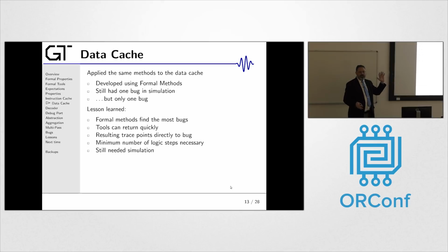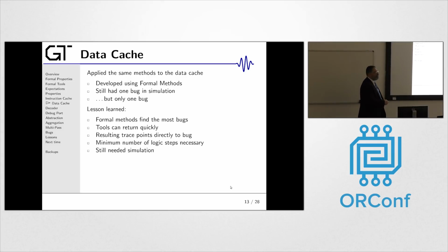Actually, I'm usually working between 1 and 10 gigabytes when I deal with traces. When you're using the formal tool, the trace is maybe 10 kilobytes. It might have 20 clock cycles in it. That's all you have to examine to figure out what's going wrong. When I got to the full ZipCPU, it was only 18 clock cycles that it took to prove the whole CPU.